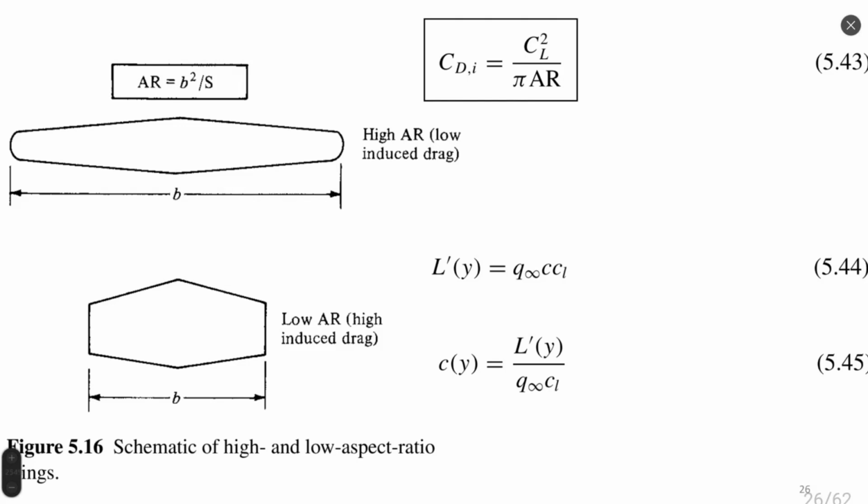For high aspect ratio wings and for low aspect ratio wings, but it cannot be used, for example, for delta wings or triangular wings, because in such cases the shape changes drastically and good accuracy of calculation cannot be achieved. So the farther we are from classical rectangular wings, the farther we are from classical Prandtl's theory, and the bigger the error associated with this geometry problem would be.